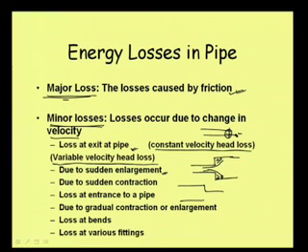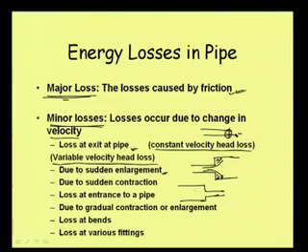So, in a pipe system we should try to avoid this sort of contraction or enlargement if possible, but definitely we cannot do that. We require this sort of contraction and enlargement. And as we require them, we will have to know how much energy will be lost at that particular point. And of course, the loss in contraction is less than the loss in sudden enlargement.